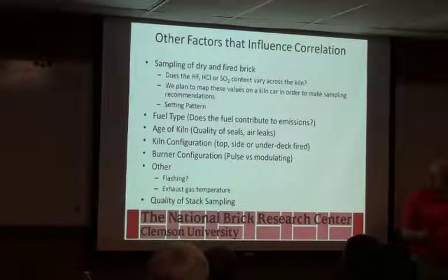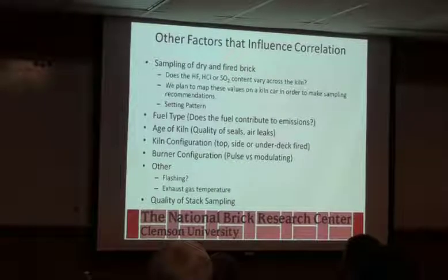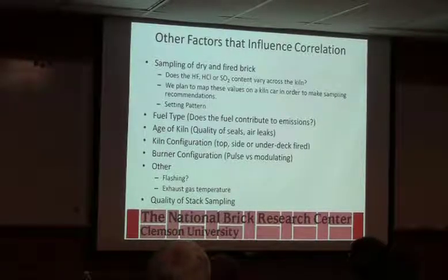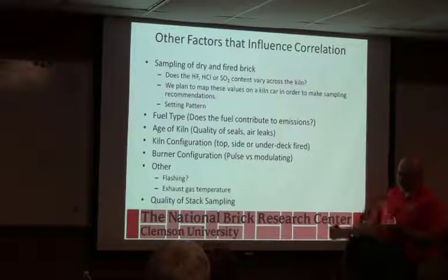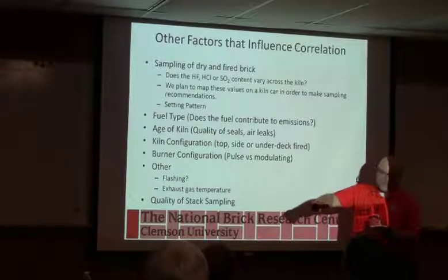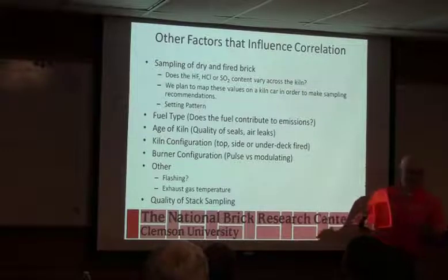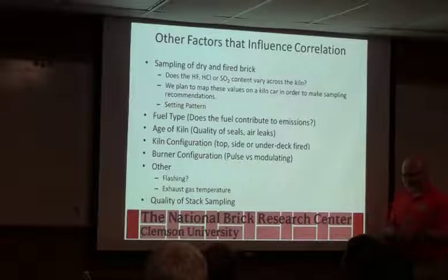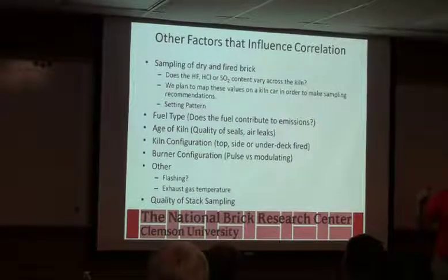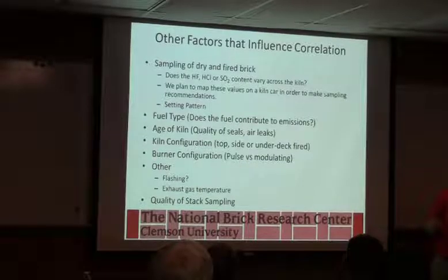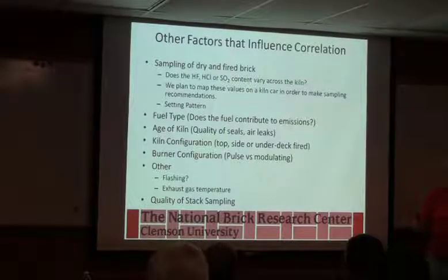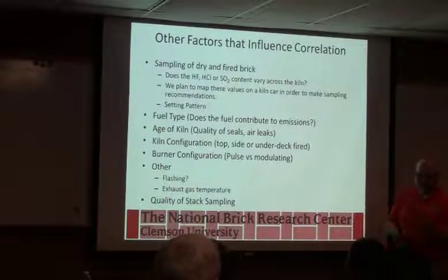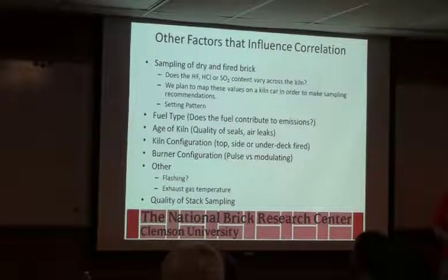So the way that the rules work, and I didn't think to include this, we go through something periodically called MACT. I don't know if any of you have ever heard that. Maximum Achievable Control Technology. Theoretically, they set a level for these emissions, and they say you have to put in a control device or somehow come below this level. Every 7 years, they reevaluate it and see if there's new technology available, and they'll lower that limit. Well, they don't really follow the technology like they're supposed to. They just lower the limit and expect you to come up with the technology to meet it. So that's a philosophical discussion that goes on with EPA.